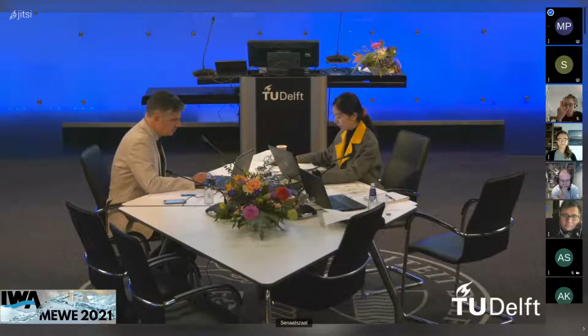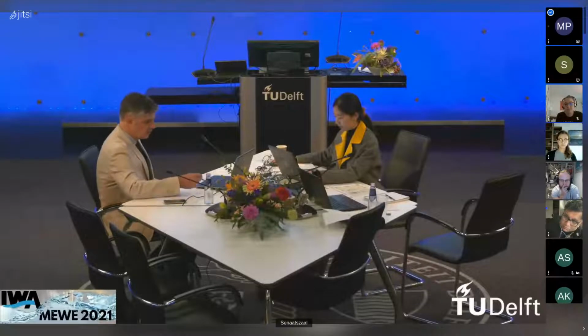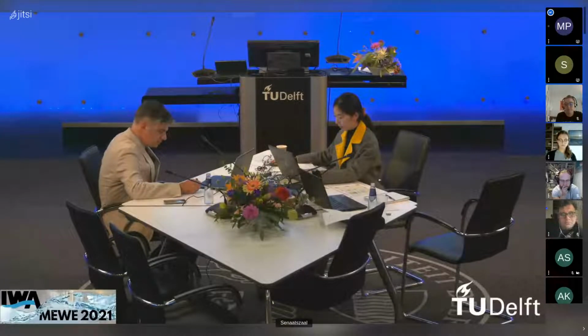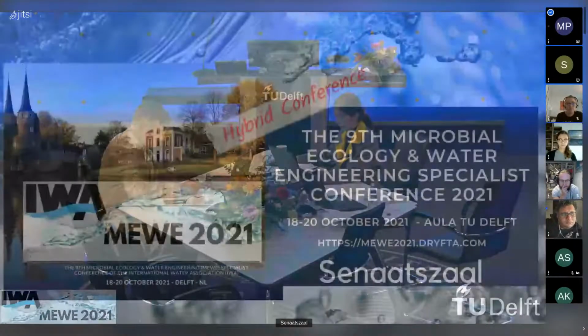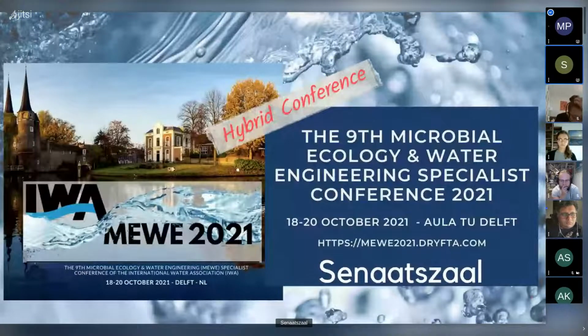So basically it stagnates about half the time. At nighttime, there's not much makeup water needed. So it stagnates, temperature varies then. So you can see that these are conditions that are prone to the growth of Legionella, especially in biofilm. You can see how deposits accumulate in such heat exchanger, and on the right-hand side you can see the results of qPCR and culture-based investigations of densities with swabs.